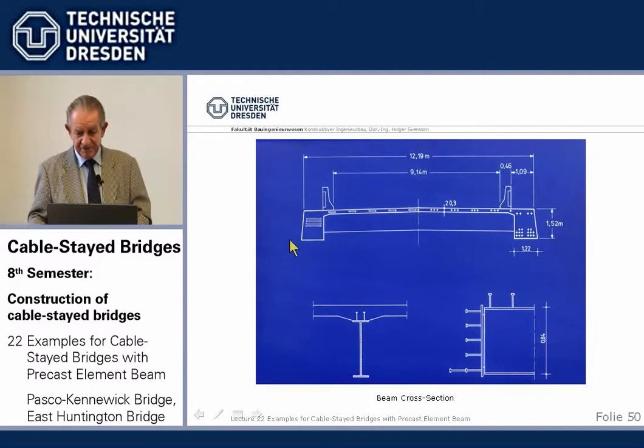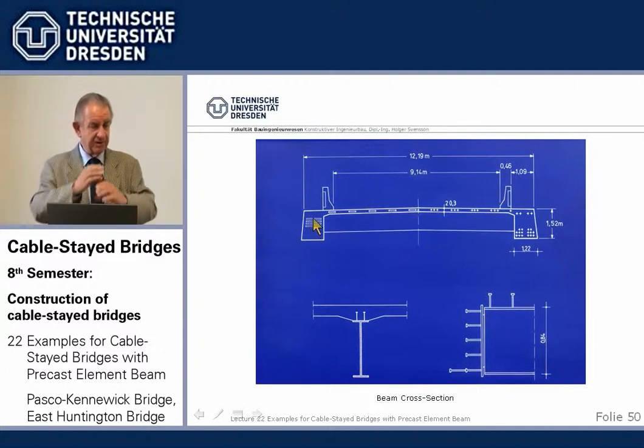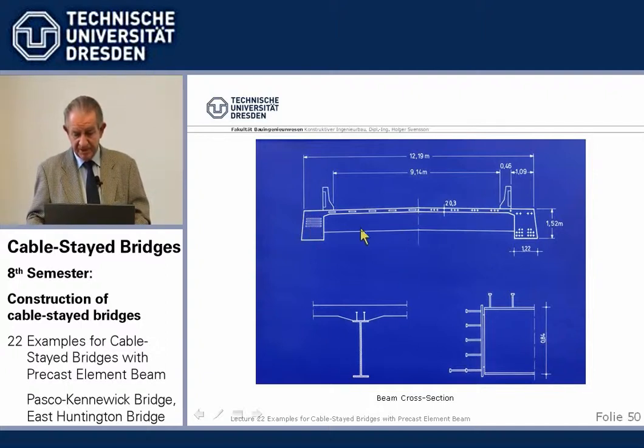Well, that's the cross-section, rather absolute minimum you needed. And here we had then, instead of the steel dowels, we had profiled the concrete to take the shear. We had the steel cross-girder like this to save weight, cast at the end the shear studs, of course not the structural steel. The concrete stops here, and the forces are carried by the shear studs.